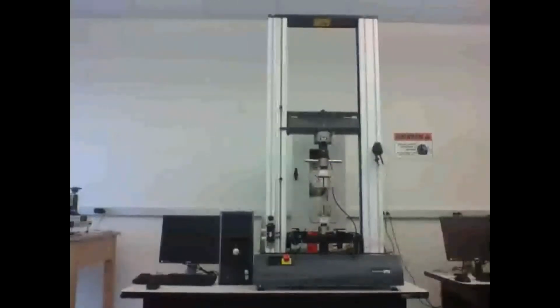The goal of this lab is to generate stress-strain diagrams using Excel for metal samples experiencing pure tension. In order to determine stress-strain relationships, tensile testing can be used. This test consists of slowly pulling a sample of material in tension until it breaks. Rather than measuring cross-sectional dimensions while conducting the experiment, we will measure stress and strain based on the original sample